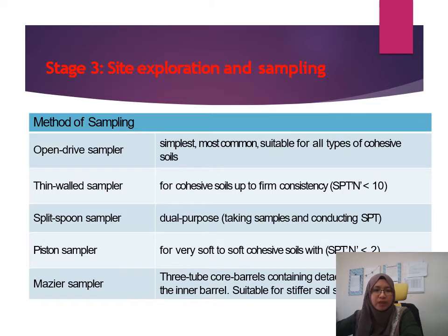All of these samplers have suitability for certain types of soil, so you have to check. For example, open drive sampler is suitable for cohesive soil, and thin wall sampler is suitable for different types of soil.